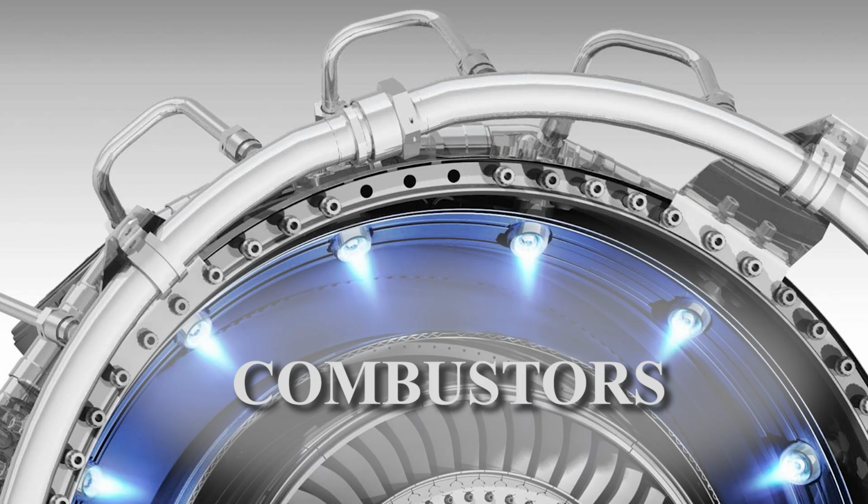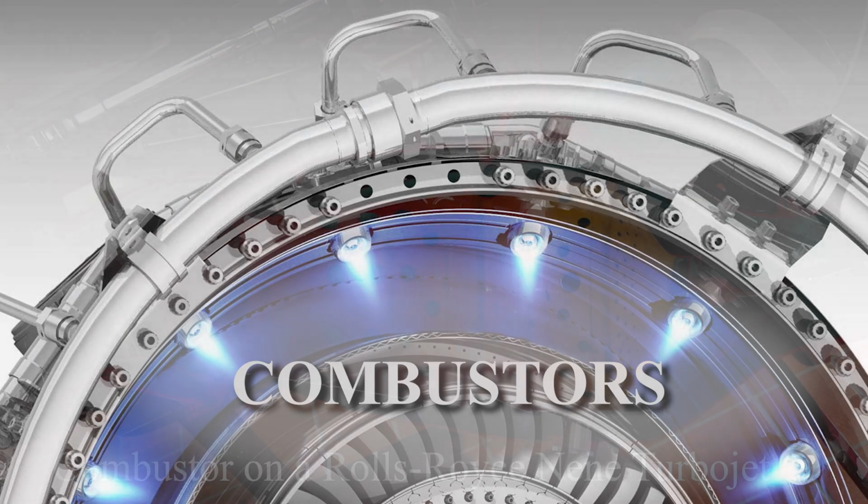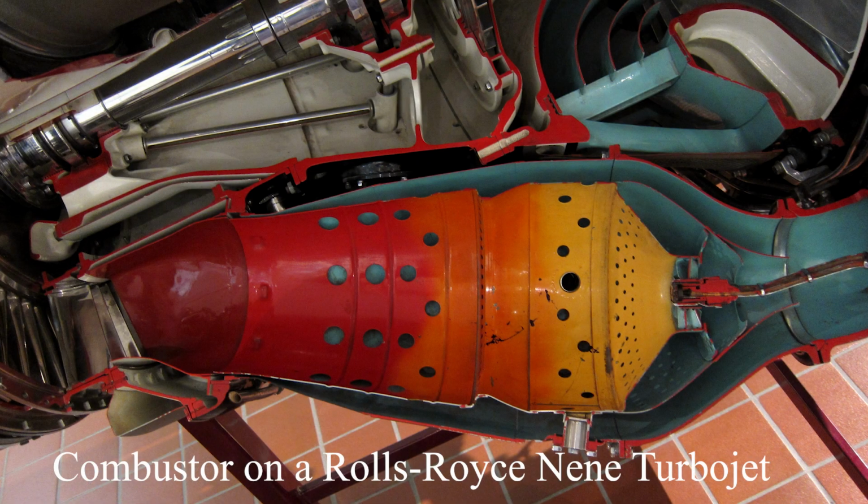Combustors play a crucial role in determining many of an engine's operating characteristics, such as fuel efficiency, levels of emissions, and transient response, which is the response to changing conditions such as fuel flow and airspeed. The objective of the combustor in a gas turbine is to add energy to the system to power the turbines and produce a high-velocity gas to exhaust through the nozzle in aircraft applications. As with any engineering challenge, accomplishing this requires balancing many design considerations.